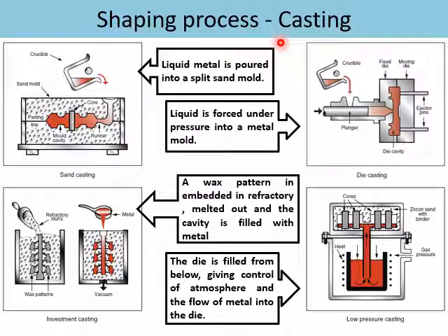After the mold is set, liquid metal such as tin, bronze, and aluminum is poured into the cavity through the inlet. This process may produce air voids. If air is not properly removed, then you have a defective product. To avoid this, multiple inlet points are suggested so that air is easily removed.